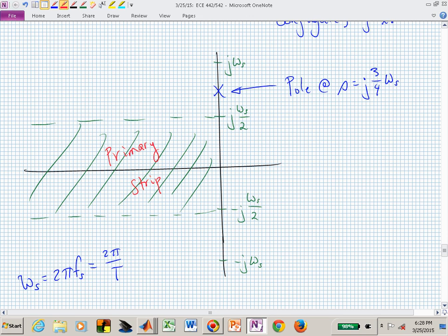Once you've started to sample, you've basically said, I don't want to know anything about what's happening above the Nyquist. So you would want to have those frequencies attenuated prior to sampling. So now you filter these analog waveforms with this anti-aliasing filter and sample now at omega sub s. Questions on that?